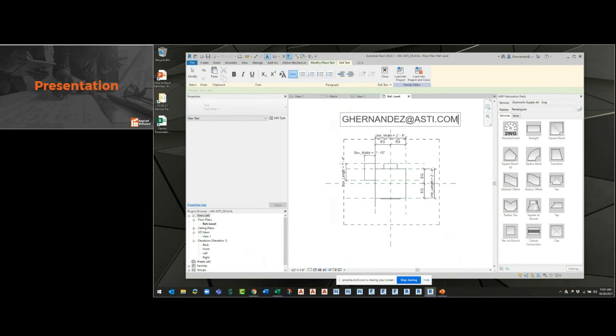If you select the wrong template type, say hosted, you cannot change that. You pretty much have to start over if you pick non-hosted versus hosted. But any of the categories, mechanical, plumbing, generic, that is interchangeable.